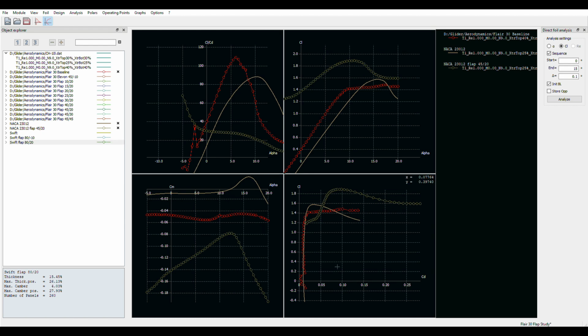And we can see the same kind of thing. Here's my original airfoil right back here. It's curved. Deflect the flap 20 degrees when it's hinged at 45%. Look where the drag goes. It goes way over to the right. It doesn't stay here and go up to a higher CL with no additional drag.